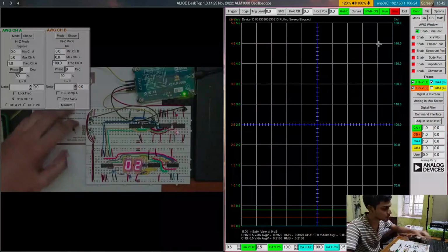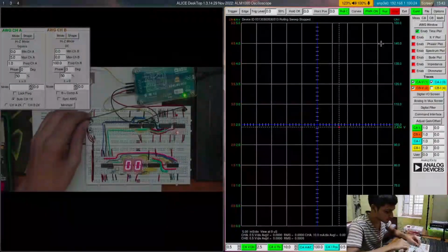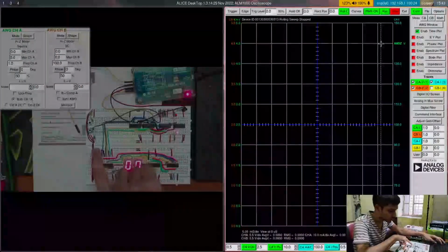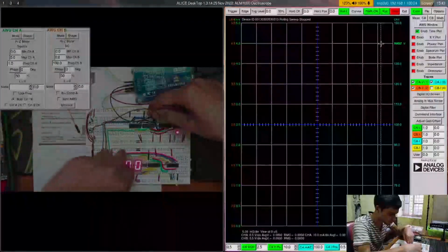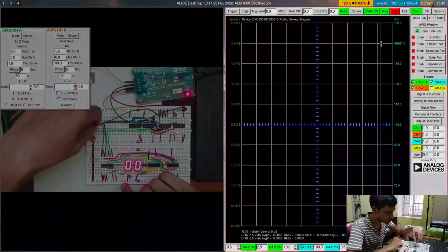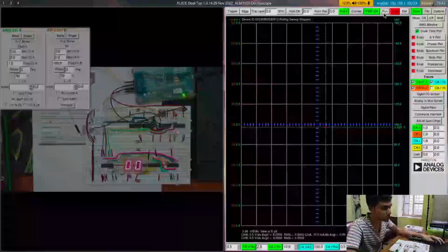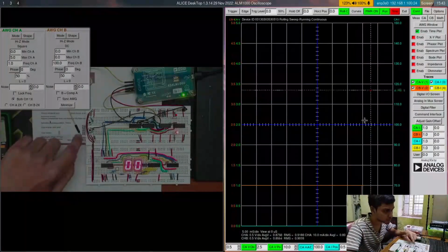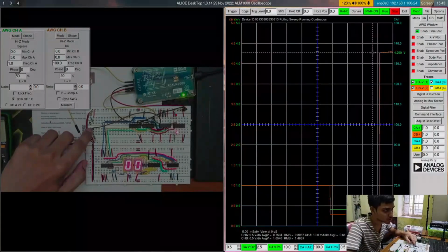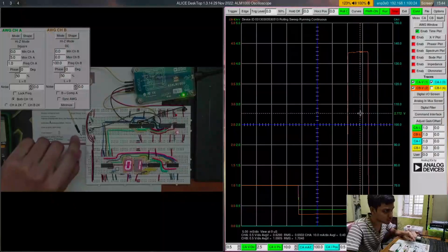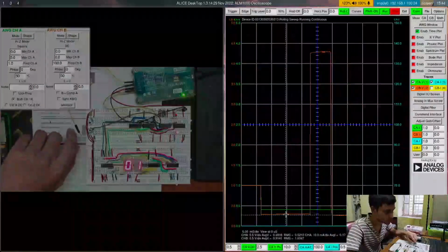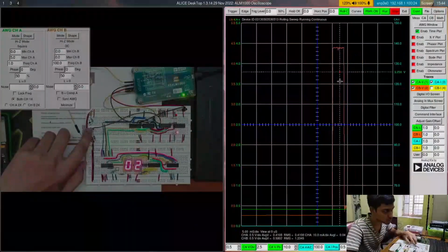And now let's check the second push button. I have connected the second push button output to the Schmitt trigger. Now let's check the push button waveform. When the button is not pressed, the value is 0 volts. When I press the button, it goes to 5 volts. On release, it goes to 0 volts. So the push button output generates a positive edge on the press, and on the release a negative edge.